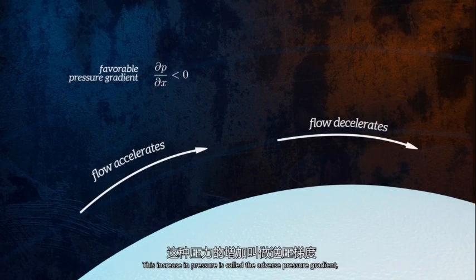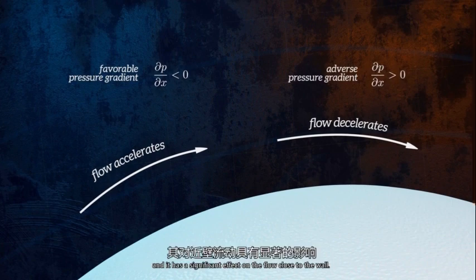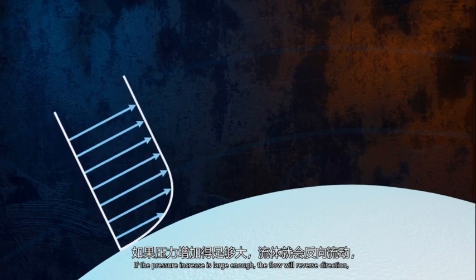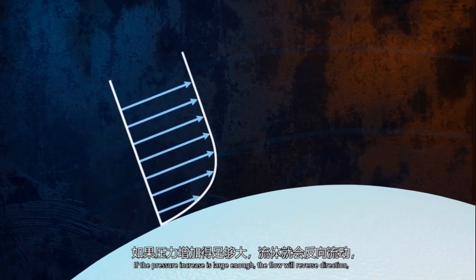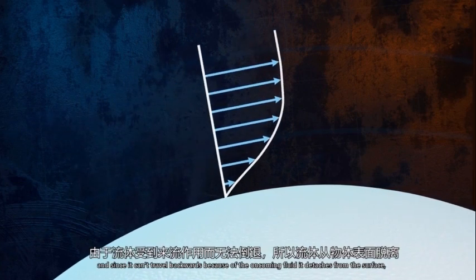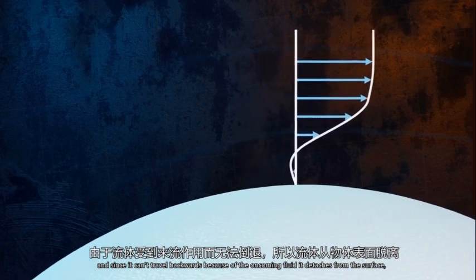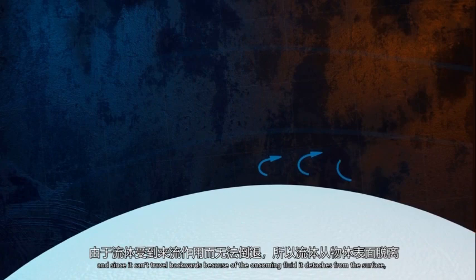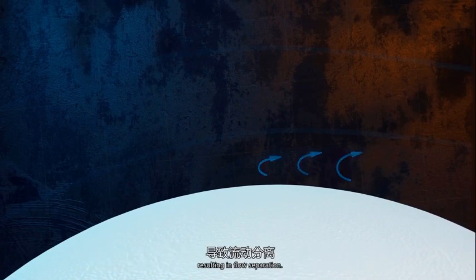This increase in pressure is called the adverse pressure gradient, and it has a significant effect on the flow close to the wall. If the pressure increase is large enough, the flow will reverse direction, and since it can't travel backwards because of the oncoming fluid, it detaches from the surface, resulting in flow separation.